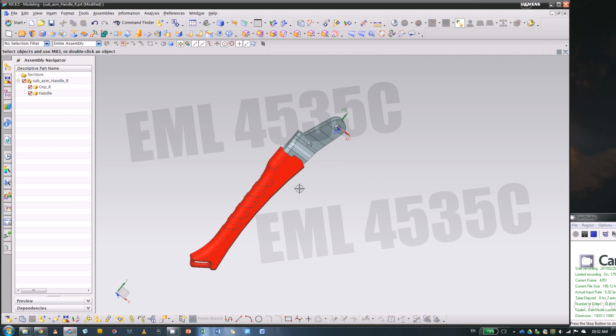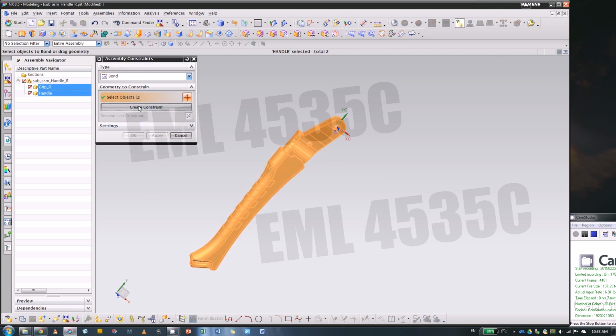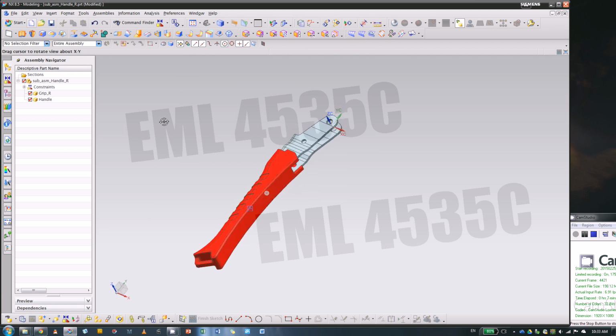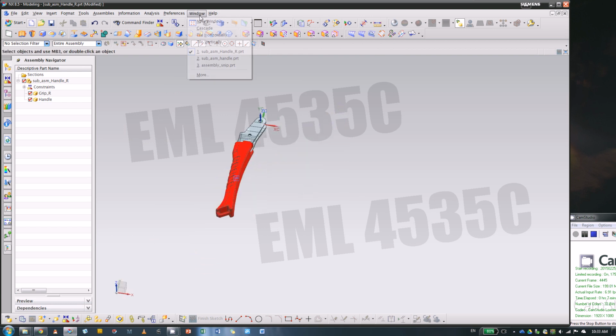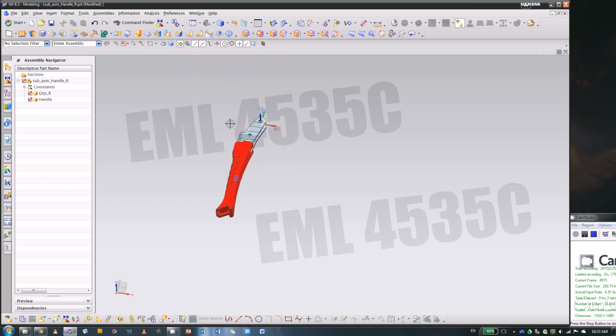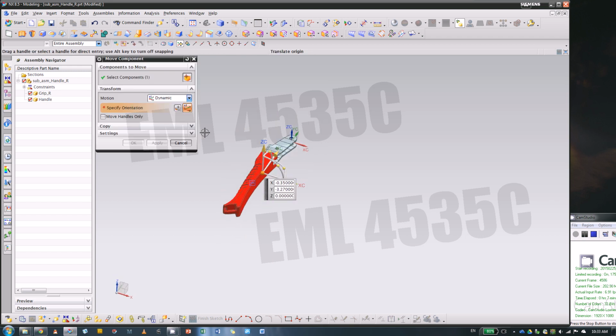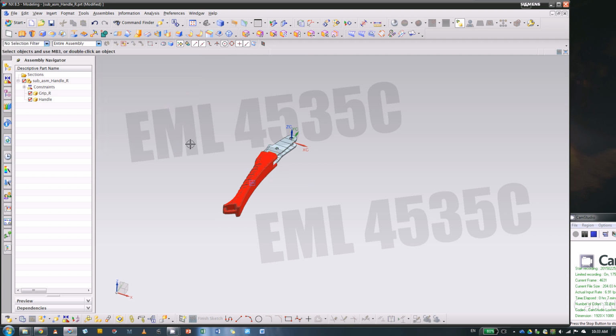All right, and again, we're gonna apply a bond between them first, so they don't move relative to each other. And if you notice, the first subassembly is on the left side, and this one is also on the left side. You can probably just rotate this now, or you can rotate that later in the master assembly or the top level assembly. So let's say we're done with those two sub-assemblies.